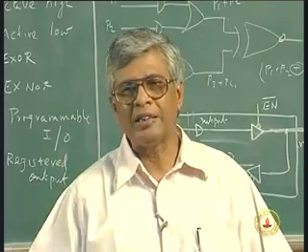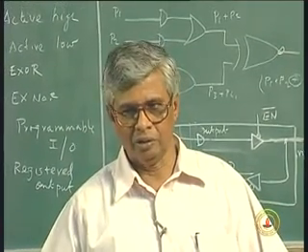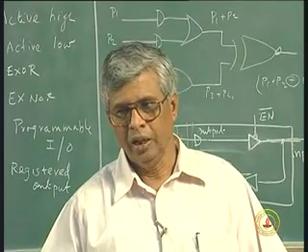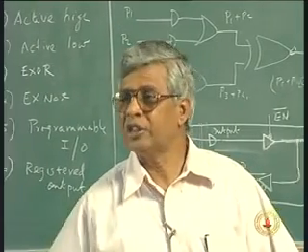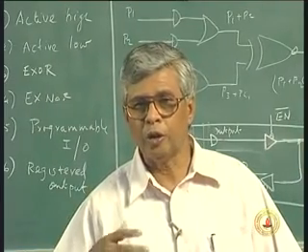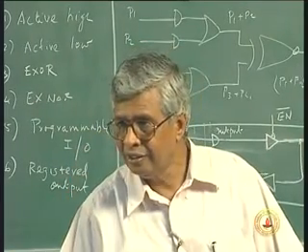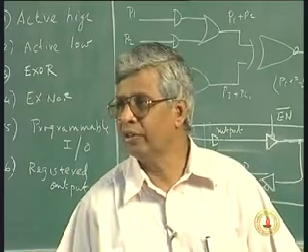ROM can be of any size, but larger size means larger memory space and power, and we don't want to use them. As I said, a large ROM is inefficient for a design, because a large ROM means a large number of inputs and all the minterms are generated. When all the minterms are generated, only a few of them are used, so it is inefficient hardware utilization.